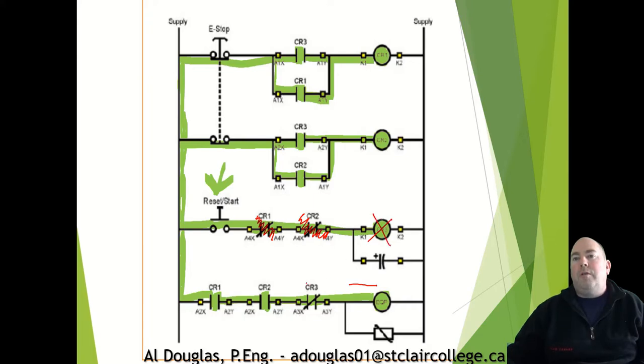That going off now closes this one. And now I get power to here. So this now gives me power to the equipment. Okay? And I will stay energized like this. The only thing that's going to break me out of it is pushing this EStop here.